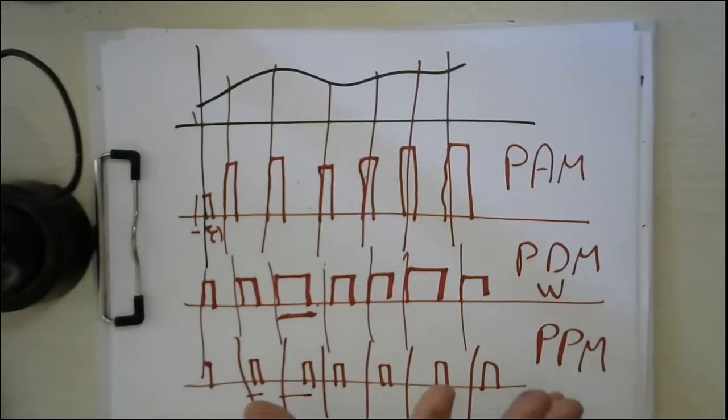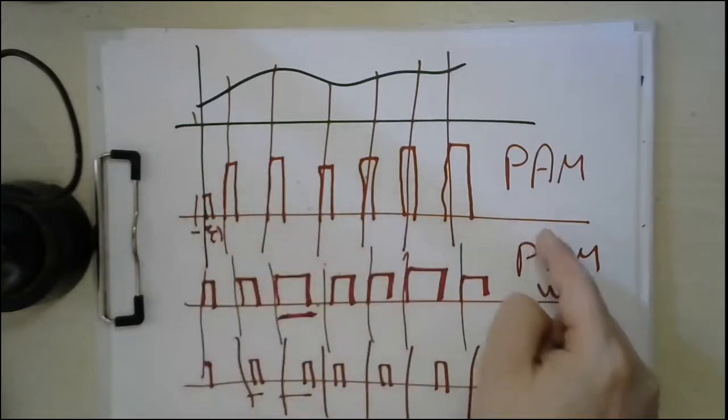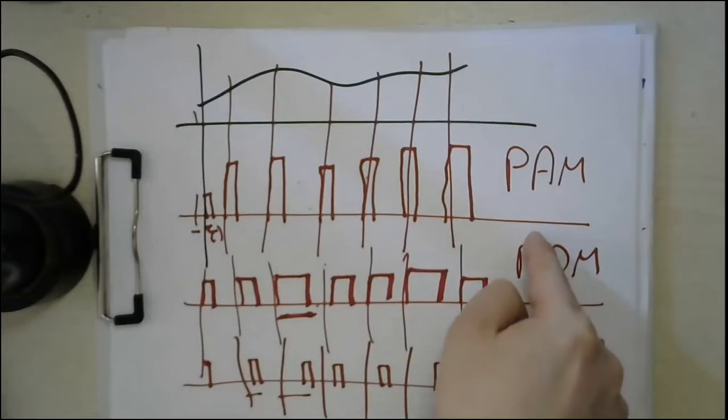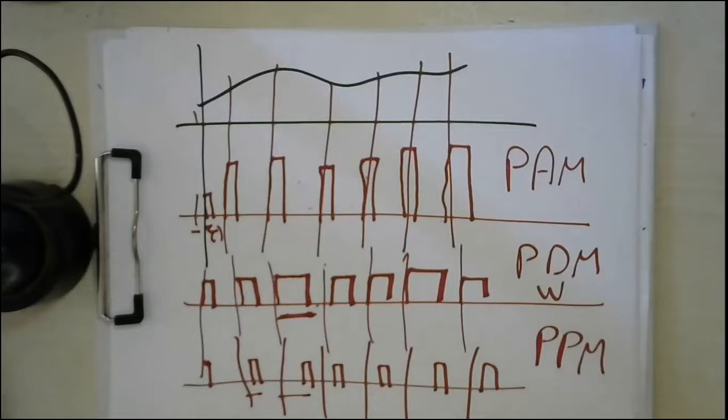Now you have a dedicated channel. You are not seeking to minimize bandwidth, so you can send impulses. What you gain is that this is very easy to modulate. For example, this is a flat top sampling: just multiply the signal with a stream of impulses, and that's all.